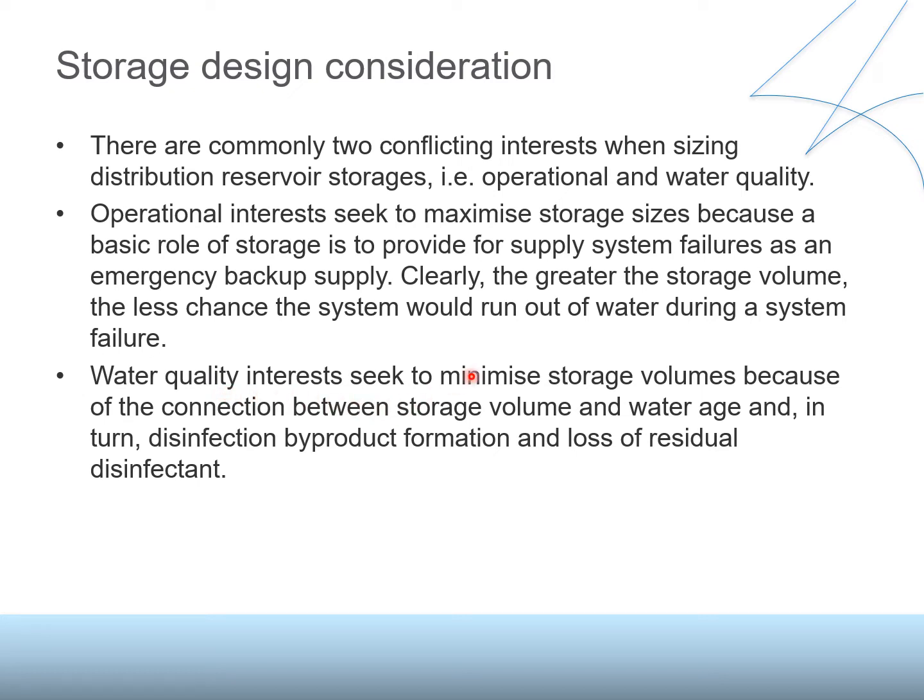We want to minimize the storage volume because of the connection between the storage volume and water age. So the larger the storage volume, the more the water age, and if the water age is higher, then the water will turn bad. It has disinfection byproduct formation if the water stays there for long, and also loss of residual disinfectant.